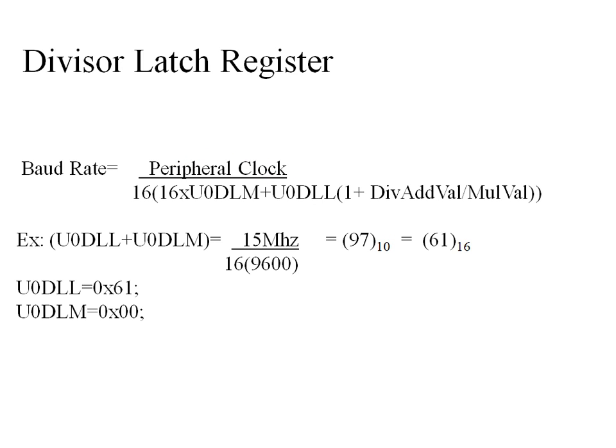Basically we use a 12 megahertz crystal. Now that frequency is given as an input to the PLL, and if we set the PLL to a factor of 5, then it multiplies it by 5, so that the output would be 60 megahertz. Now that 60 megahertz will be given as an input to the VPB divider.